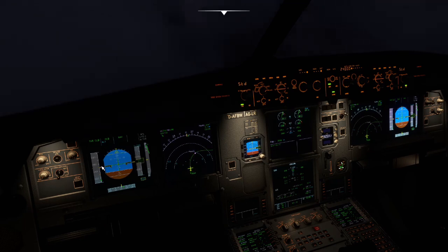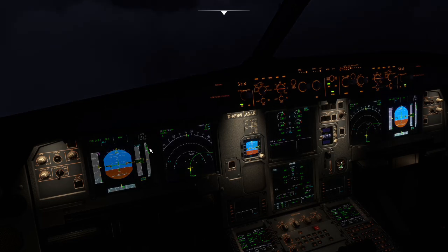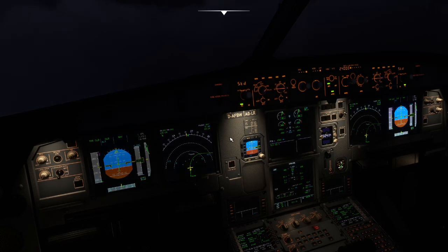Through 10,000 feet, the 250 below 10 limit will kick. You'll notice the speed indicator kick up to our cruise climb speed, which I think is around 290. And the jet will push the nose down to accelerate up to that new climb speed.